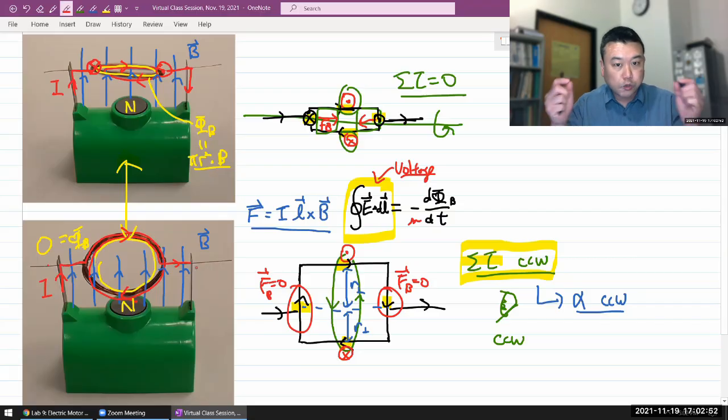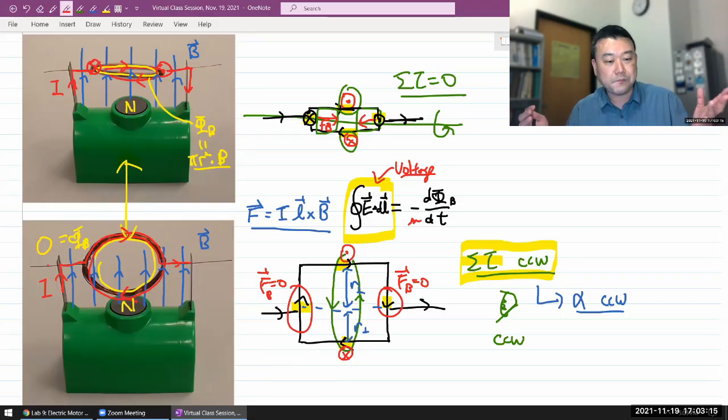So there comes some equilibrium speed where the applied voltage equals the induced voltage that's opposing that applied voltage. And at that point, the whole thing is not going to really draw all that much current. If you imagine a perfect coil of wire, a perfect motor that's spinning frictionlessly, then there's an equilibrium speed where the coil won't be drawing any current because the voltage you are applying is precisely opposed by the back EMF.